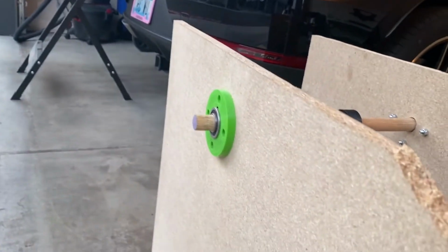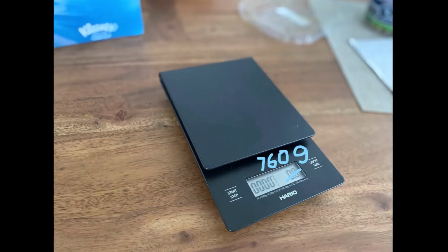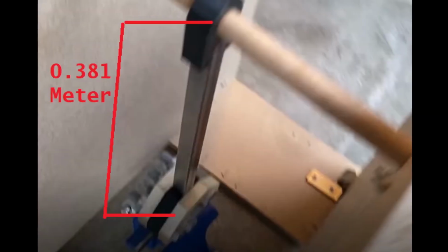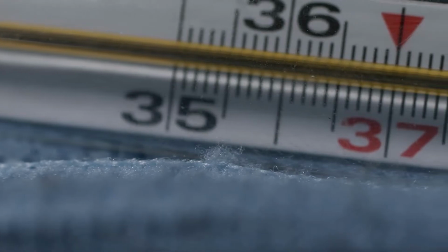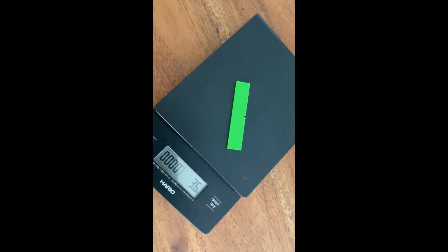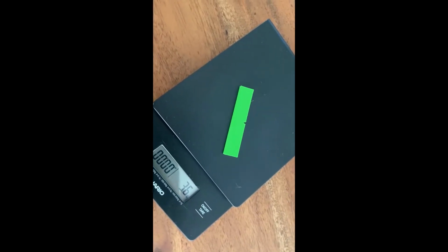The test conditions are controlled by many variables. There's the mass of the striker, the height at the starting point, the temperature, and specimen dimensions. I'm going to have specimens based on an online image. To get a better understanding of impact strength, I decided to make an impact strength tester and try it out.